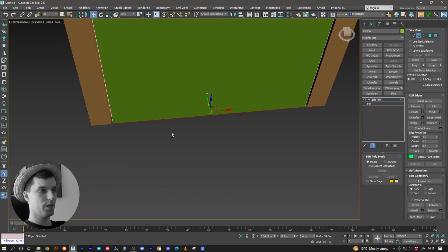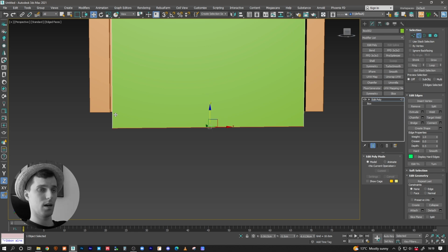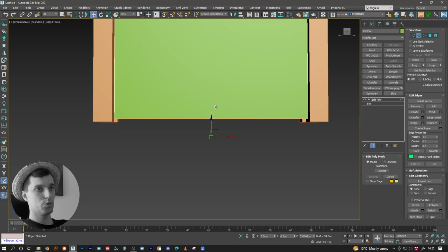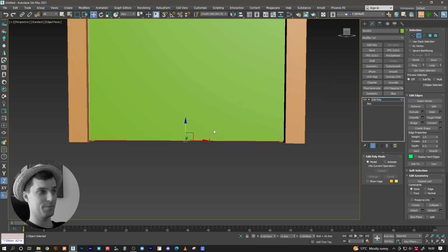Another very important thing: never ever leave the door flush to the floor, because you're going to be adding tiles or whatever. Even in reality, builders usually leave 2 to 2.5 centimeters of a gap between the door bottom and the concrete floor, because people usually add thick carpets, tiles, hardwood flooring that's 1.5, 2 centimeters, etc. It depends on the quality, how expensive it is, how thick it is. So you want to leave a gap here, even in a 3D world, right?